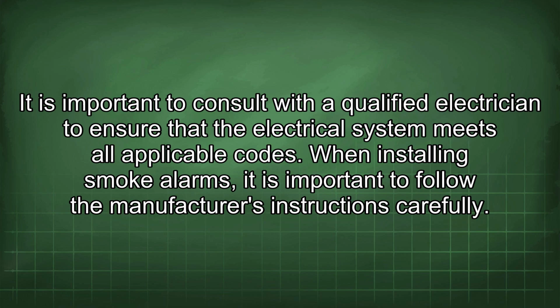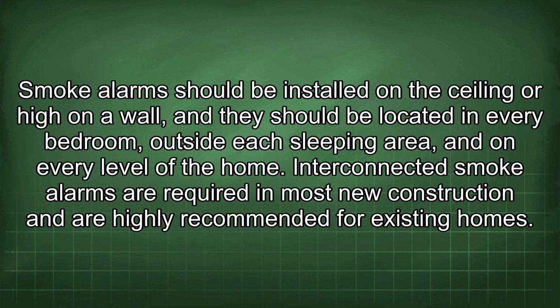When installing smoke alarms, it is important to follow the manufacturer's instructions carefully. Smoke alarms should be installed on the ceiling or high on a wall, and they should be located in every bedroom, outside each sleeping area, and on every level of the home.